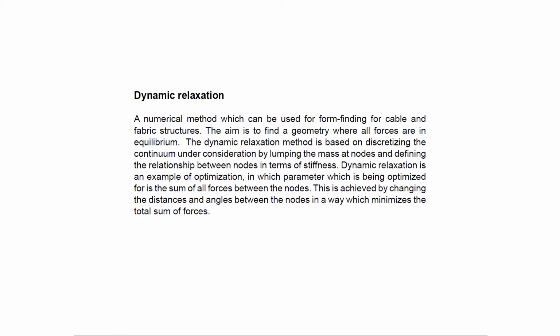Okay, so if you have a static structure, that means all forces inside the structure cancel each other out. So the structure is not moving, it's a static structure. And of course, in the realm of architecture, those are the structures that we are interested in. The ones that don't move, they're kind of what we build, or how we build things. Okay, but how to find the shape where all the forces are in equilibrium is an optimization problem. Also, we need to find how this surface looks like.